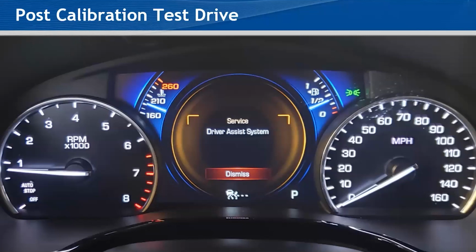The argument I hear a lot is, well, if the car was calibrated when it came right off the line, everything was calibrated, and then we just replaced the windshield, and I got a really good windshield guy, and he didn't have to touch the camera because it doesn't have to move. Why would I need to change anything? Well, I'm sure the suspension has settled and changed. And just think about if it was perfectly in line from the factory and now it's still green, but that's 0.2 of a degree this way and a little bit of caster and a little bit of camber and all the things are all different.